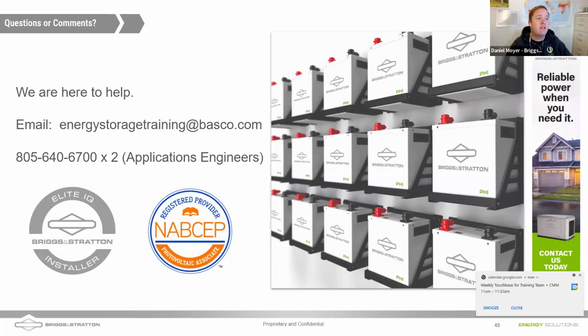Patrick asks, so when the batteries are charging, they cannot be supplying power to the house? Yes, a battery cannot be charging and discharging at the same time. So if the generator is running a charge cycle on the batteries, it also needs to be covering the loads in the house. Now, if you had DC solar on the house, that DC solar could potentially cover the loads.